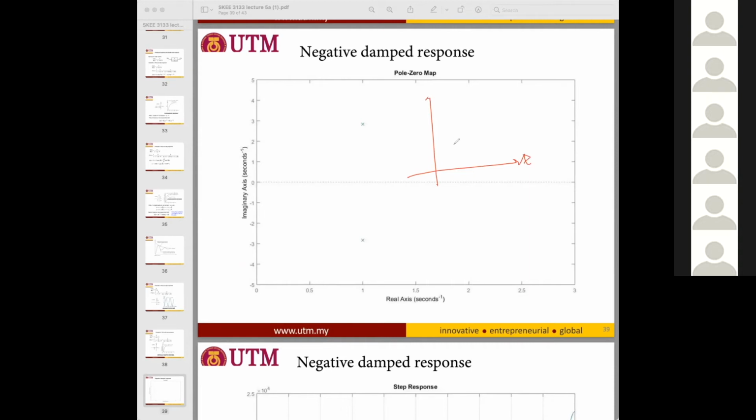Okay. Then you have a graph, something like this. So you have to identify the parameter values: settling time, peak time, time constant, to get the mathematical model G of S.